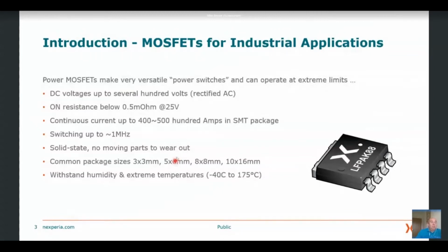And they come in a range of different package sizes. Of course, you can get very small signal MOSFETs, but for a power device, typically from about 3 millimeters square up to the big D2PAKs, which are about 10 by 16 millimeters.